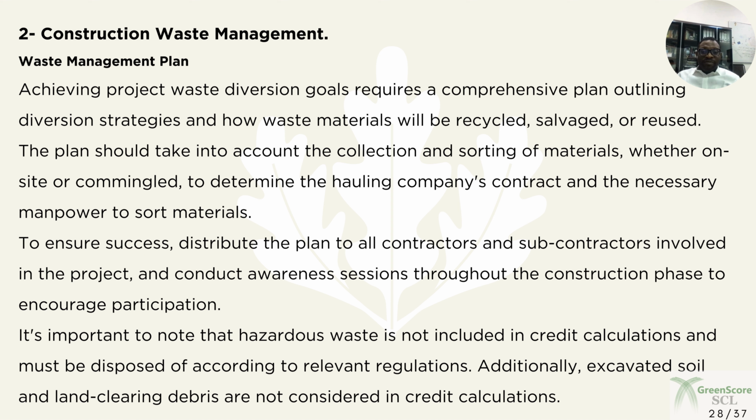There is need for a comprehensive plan that details the diversion strategies and how waste will be recycled, salvaged, or reused. The plan should take into account the collection and sorting of materials, whether on-site or commingled, to determine the hauling company's contracts and, of course, the necessary manpower to sort the materials.